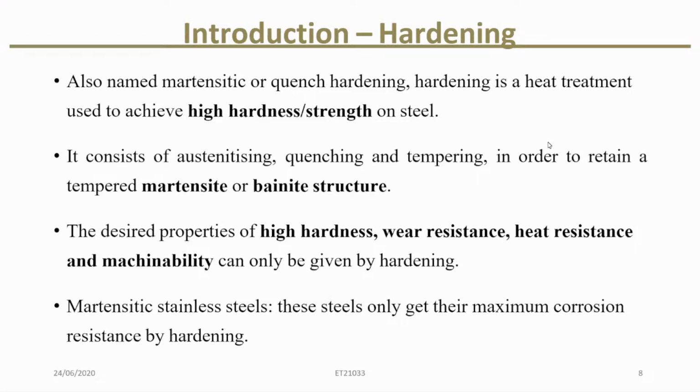As a medium, we can use oil, water, or gas. So the austenite turns into martensite. That's the super hard phase. Okay, then the final stage is temper. Temper means reheat to a moderate temperature to reduce brittleness and set the final balance of hardness and toughness.